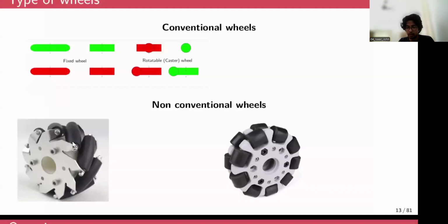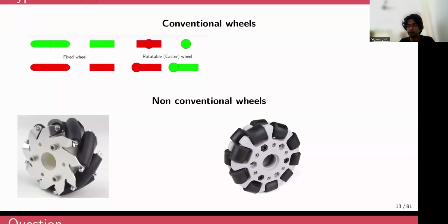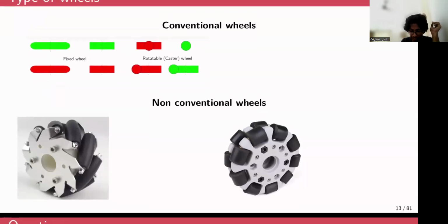All right. Okay, so in the later part of the course, we have also considered different kinds of wheels. Until now, we have talked about conventional wheels, right? The main assumption of a conventional wheel is that, if you consider this to be the longitudinal section of a wheel, and these are the wheel hubs, while modeling a conventional wheel we assume infinite resistance along the lateral direction.